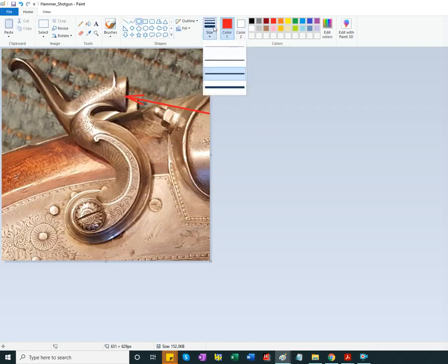two areas of tensile stresses, one here and one here, as well as compressive stresses opposing. Now, what I want to emphasize is that the radius of curvature here is less than it is here, because the bending stresses would be less when evaluating the curved beam stresses in this area than here.